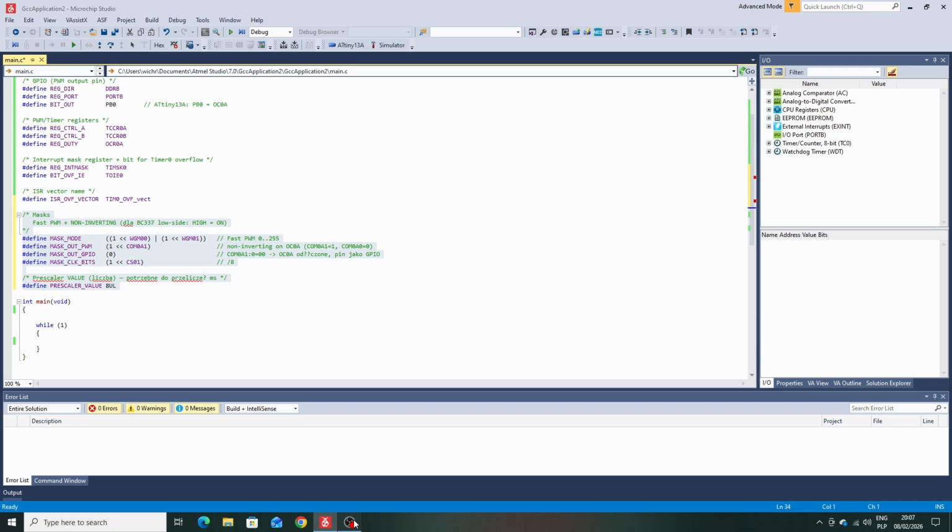And another mask selects the clock prescaler. This makes the code easier to read and safer to modify. The timer configuration becomes explicit and intentional, instead of being scattered as magic bit operations throughout the program.